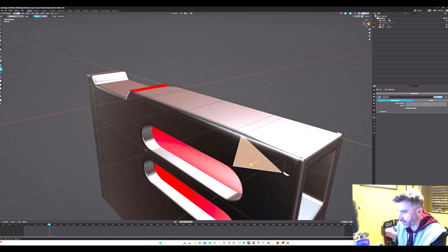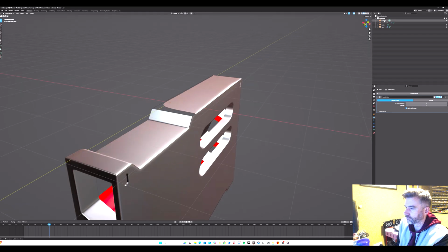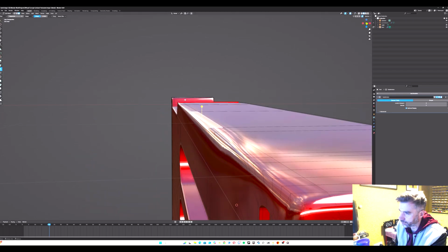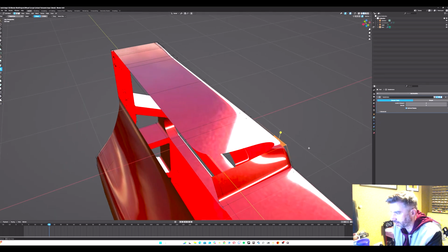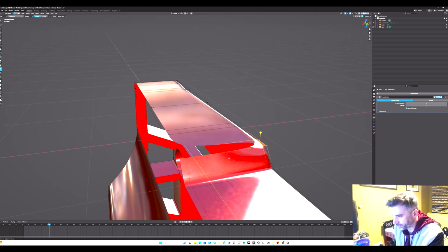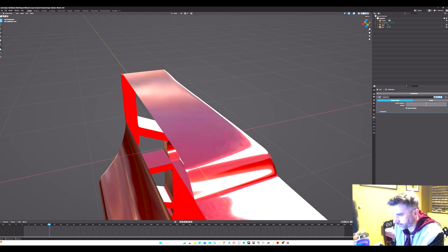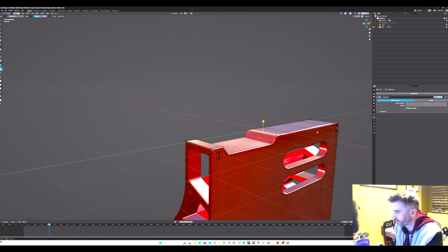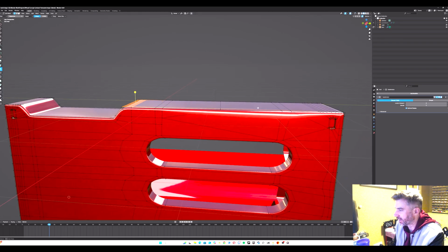Still something a bit off here. Just checking I've not got overlapping faces or anything anywhere. Just going to switch to a different matcap to see if that helps me see what's going on. Let's finish connecting and see if that fixes any of our problems. I don't think it will, but you know, you gotta hope, haven't you? Oh, I mean, it's because we have no supporting edges, so yeah, it's kind of on me. All that big talk about how it didn't matter. Turns out it absolutely matters.